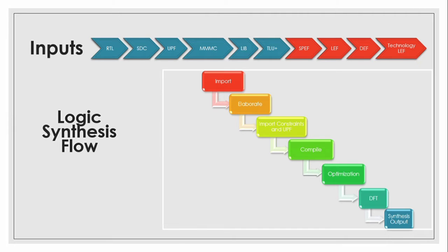RTL, as we know, contains all the circuitry definitions and all the module definitions, ports and pin definitions. SDC contains the constraint files. It contains all the constraints related to timing, power, PVT corners, design rule constraints. Everything will be there. Then comes power domain information, different voltage information, supply ports, nets, all the low power design cells. All this information will be given in the UPF.